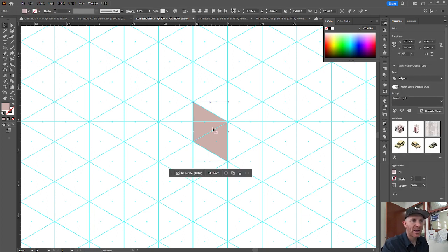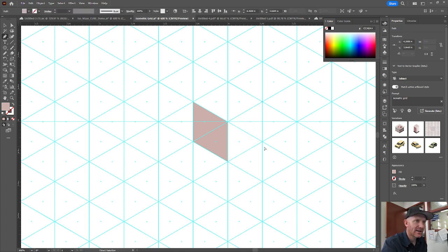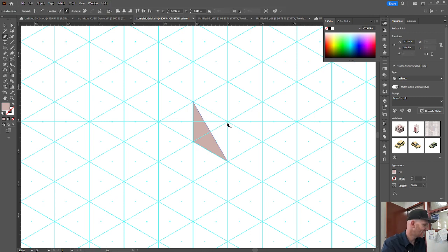Now here, with the shape selected, we're going to continue using the pen tool, but we want to make sure that we don't click on an anchor point that's previously existing. So I'm going to hit P to get my pen tool again. You can see it right there. I'm going to click on a location that's away from the shape that I just built. That way it gives it time for that shape to get deselected, so I don't accidentally get rid of an anchor point. If I don't deselect and I start here, it'll actually delete an anchor point, and that's not something I want to do.